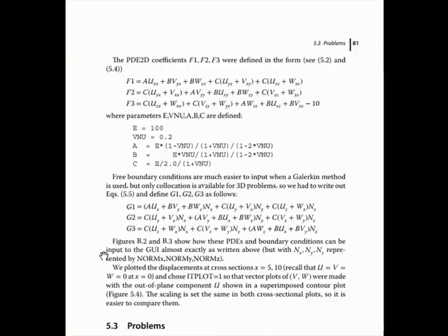In other words, we have the derivative of sigma xx with respect to x, plus sigma xy with respect to y, plus sigma xz with respect to z, and we're going to have to actually differentiate those. Well, the E and the nu are constants, so it'll just be second derivatives on u, v, and w. And it's kind of a mess, but I've written it out for you here.